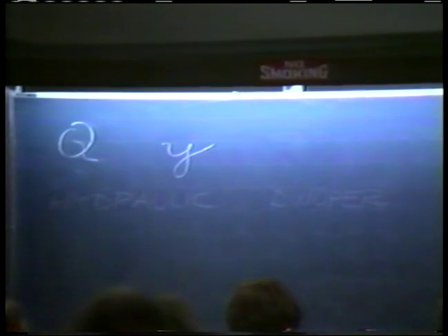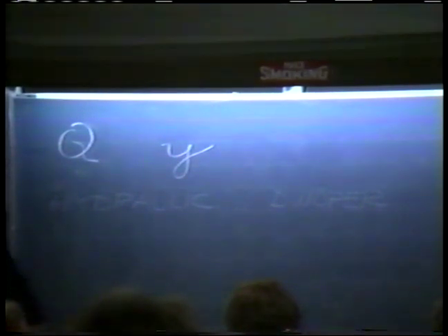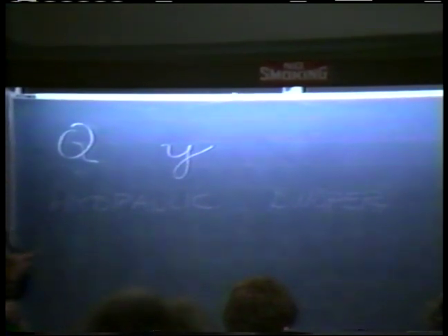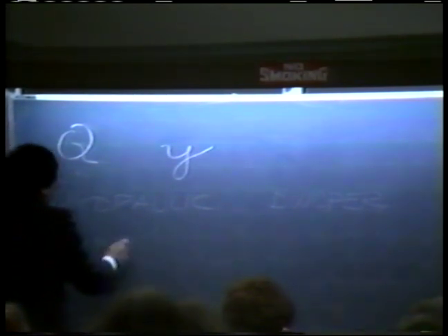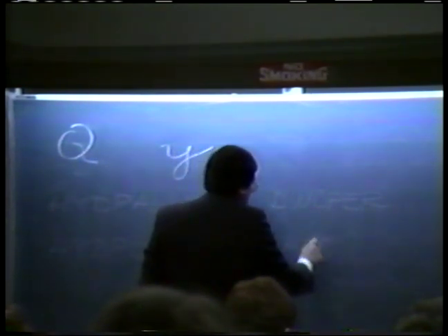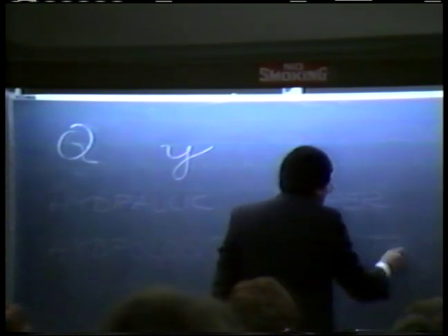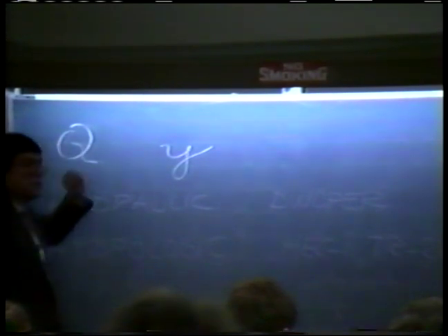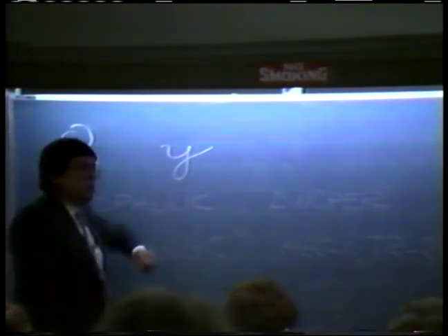On the other hand, you can choose the simplified route, which is to calculate the discharge first and then use that discharge on which to base your calculation of the stage. And in that sense, it is simplified, obviously, because it implies the uniqueness of a rating. And in that case, we say that that approach is hydrologic. Such an approach would be used, for instance, in the hydrologic models in current use, for instance HEC-1, TR-20, as well as others. They will calculate the discharge first, and then use that discharge, and through a rating, calculate the Y.